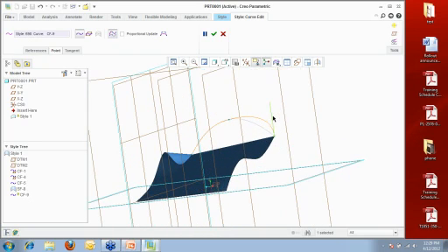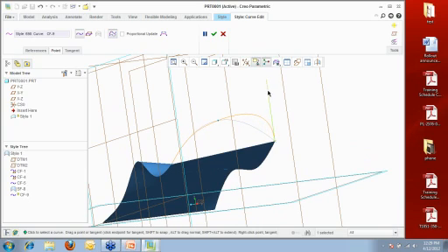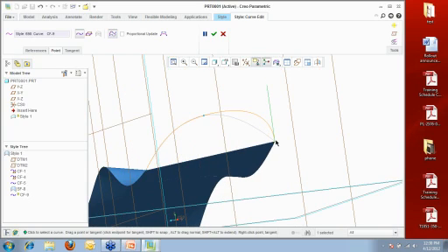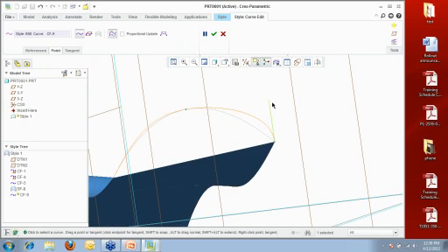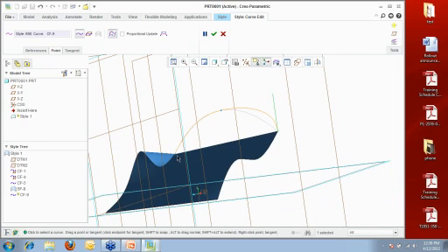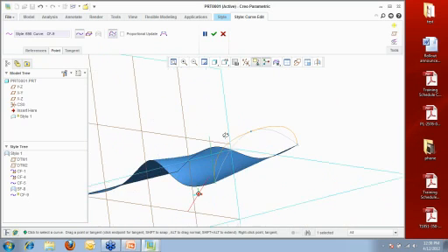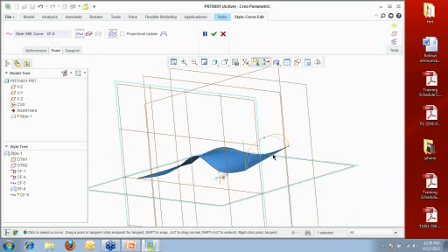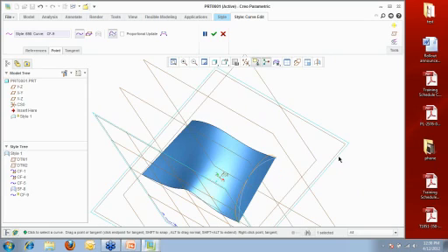Notice how now that it's normal, I also have the ability to control the length of essentially the takeoff angle for my normality, I guess you might want to call it, for that specific surface. If I come to the other end, I right-click on it and say normal, normal to what? Normal to that plane, and notice how I've now created this surface where at the ends, let's say we were mirroring a surface about this plane, it would mirror just fine because now I'm normal.